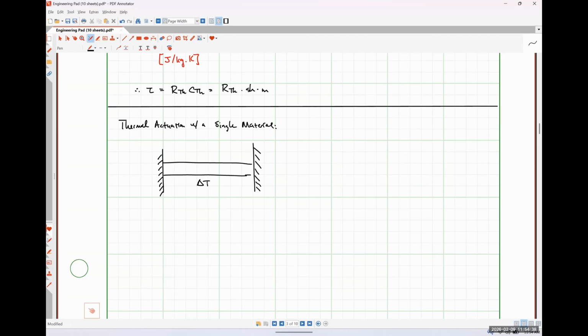So in this system, where this is our x direction, the strain produced in our x direction should be alpha, our coefficient of thermal expansion that we talked about when we were dealing with thermal sensing, times our change in temperature. Okay? Nothing real wild or crazy there. However, if we don't allow the material to expand, the total strain must be zero. Okay?